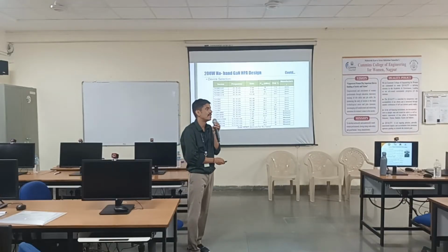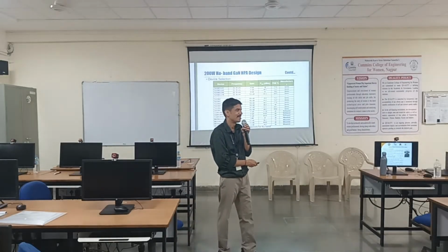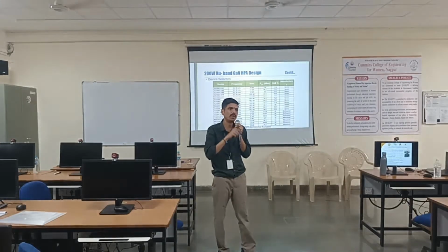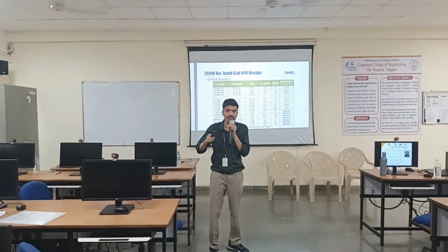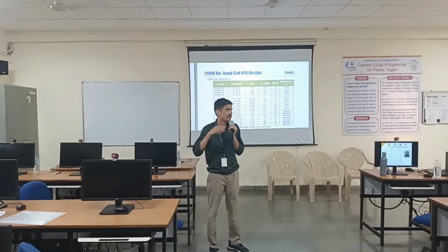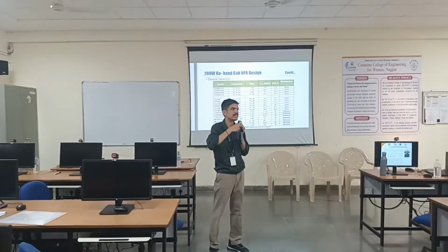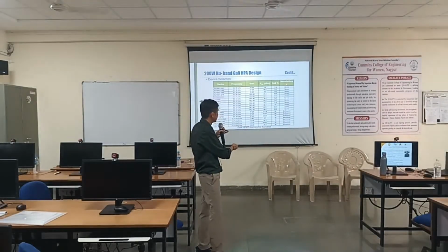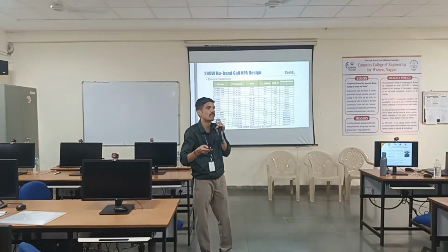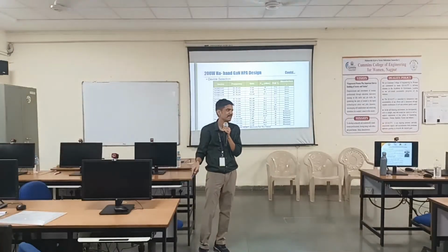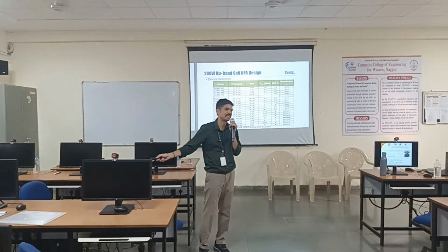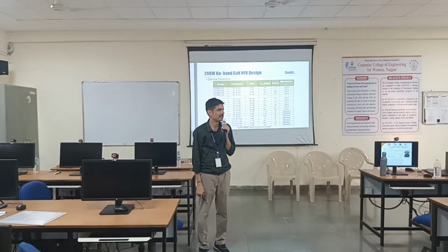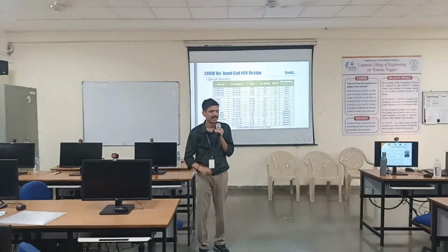First, you have to have a valid ADS. You should not use a cracked one. If you have a pirated one, they will not give a non-linear model. So you should have a valid tool license, you have to give the MAC ID of your PC where you will be using that software. Those things with your signature and your supervisor's signature, you have to submit to Qorvo. They will review it and then only they will share the nonlinear model. You should work on that terminal only. Even inside SAC, if I change my system, that model will not work anywhere else. Isn't it complicated? Somehow we got it.